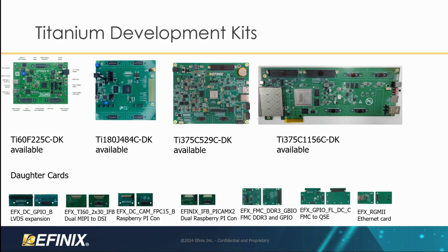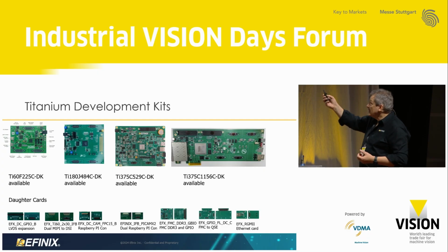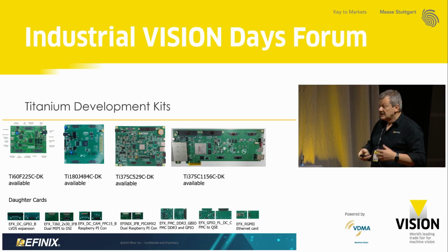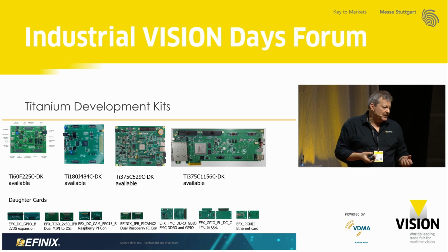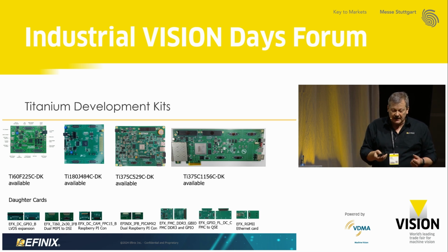We have this SFP Plus cage for 10 gigabit Ethernet and FMC connectors where you have access to an additional 8 high-speed SerDes channels and user IOs. And on the right-hand side, the QSE connectors. Here you can connect our MIPI interfaces up to 2.5 gigabit.